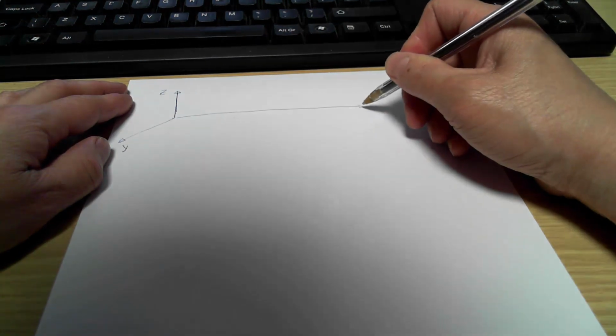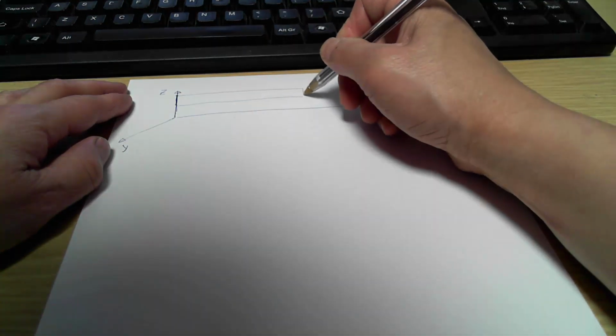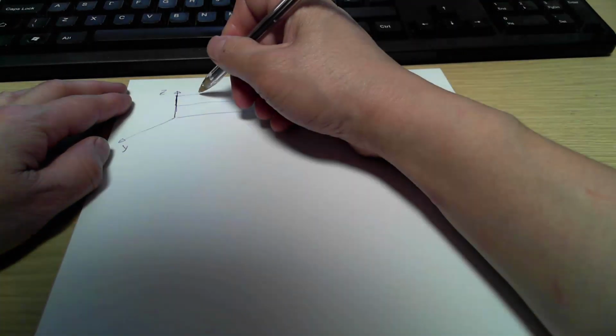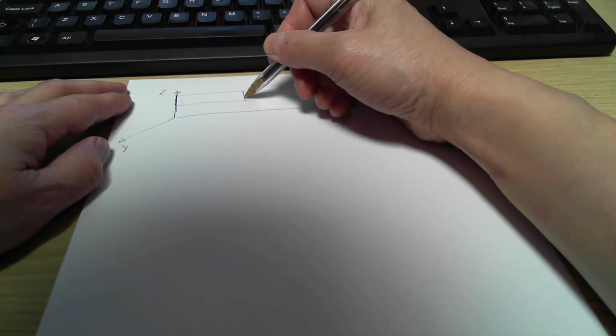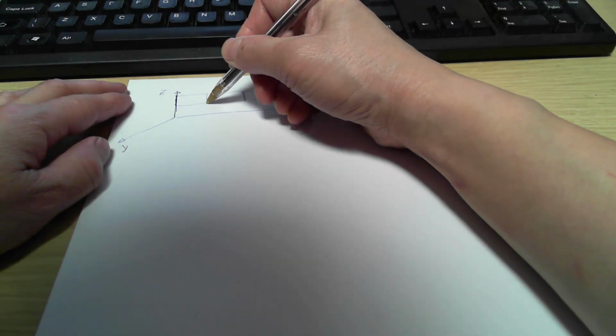So what we've got is the Z direction, and Y is here as indicated in Autodesk Robot. So this is the Y direction, and that is the X direction. The truss structure runs from here to here, 4 meters above the ground. Let me draw the outline of the structure here, and there will be a foot base at roughly 2.5 meters here, and here, and here.